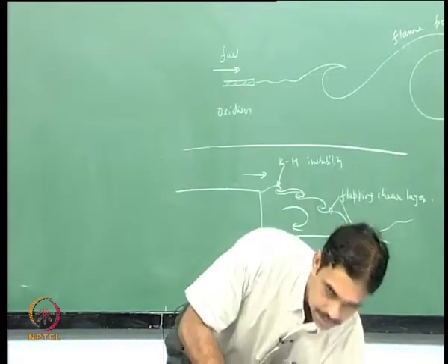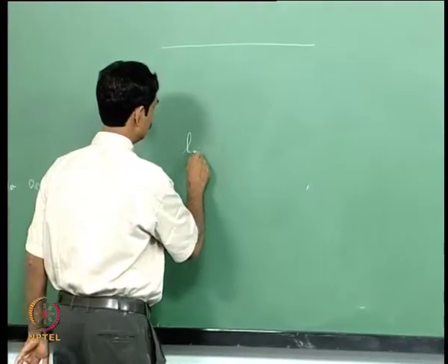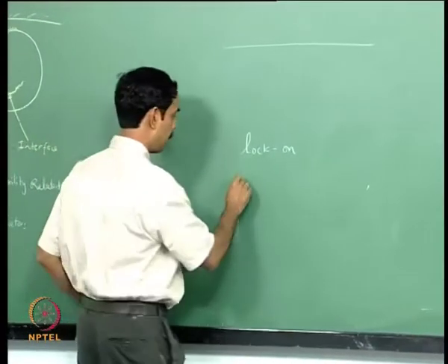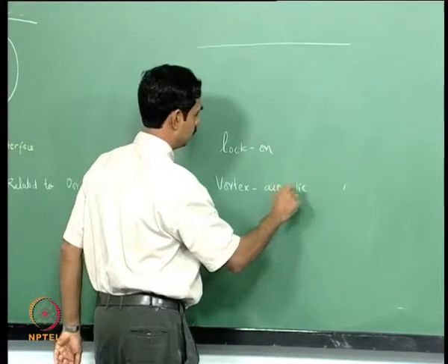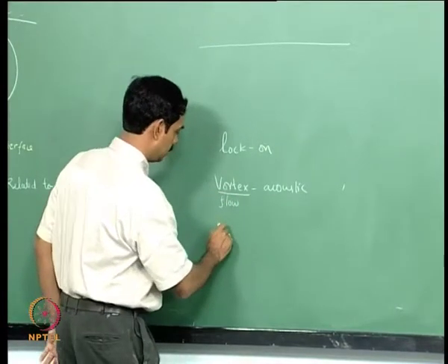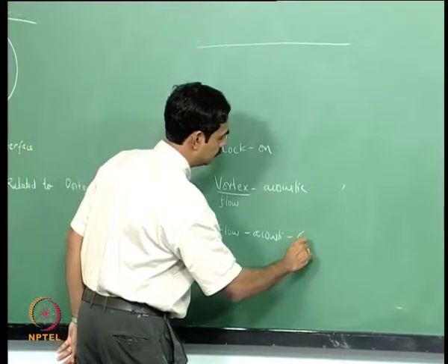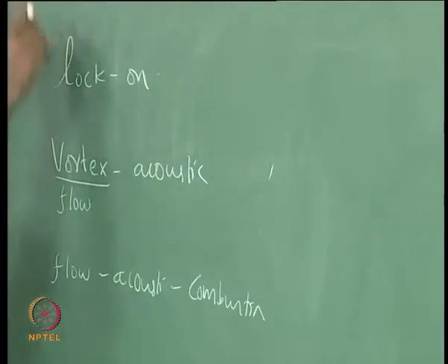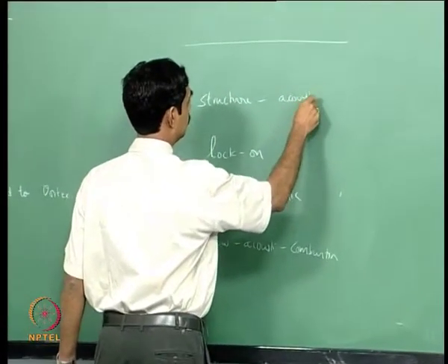So in general there is this mechanism called lock-on. We are talking about vortex acoustic or flow acoustics, and there is flow acoustic combustion, so all three can lock on, or you can have structure and acoustic lock on.